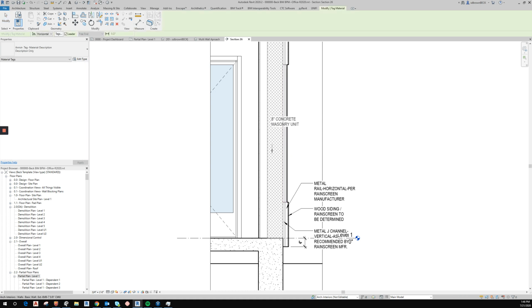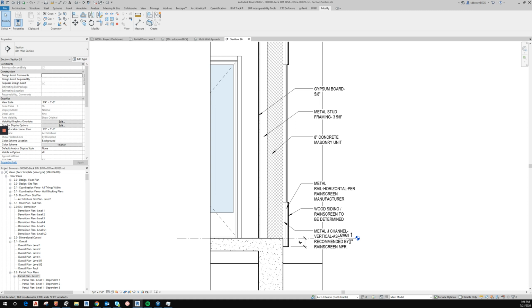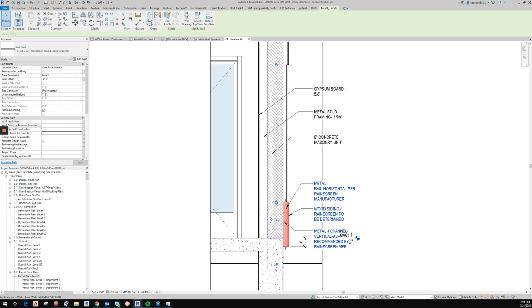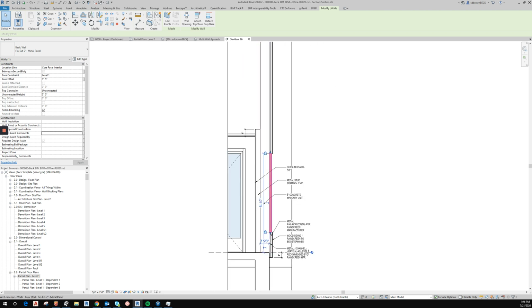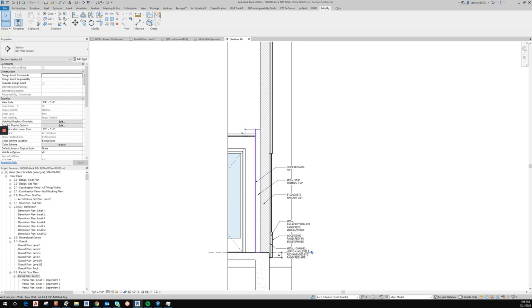The last point I'd make is that this approach actually takes fewer wall types than if you were to try and do this with a composite wall assembly, because to make up this wall, you would need a wall type that's rain screen over CMU over metal stud with gyp interior. Then you'd need to split that at this level, and you'd need one for metal panel over CMU over blah, blah, blah. So you get the idea. And you couldn't ever get this granularity in the finishes.